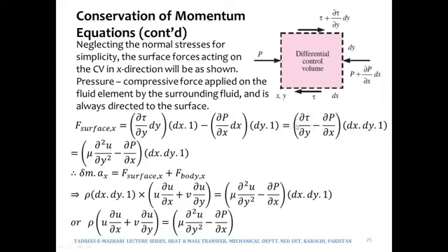And then using that particular equation which you had probably for the first time seen in the fluid mechanics course, and this is the same expression that we also had discussed in the initial slides of this particular chapter, where tau was mu times ∂u/∂y. So therefore ∂tau/∂y would be the second derivative of velocity with y, where mu would remain mu, minus ∂p/∂x times the volume.